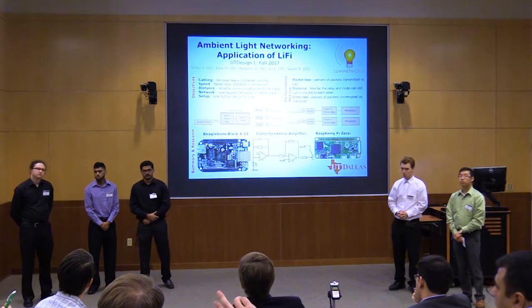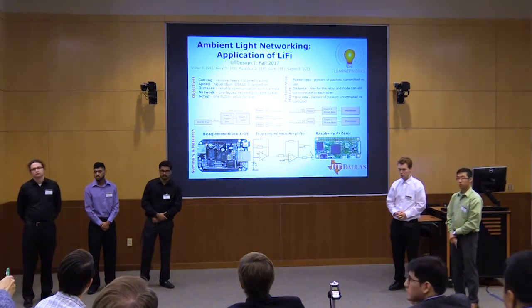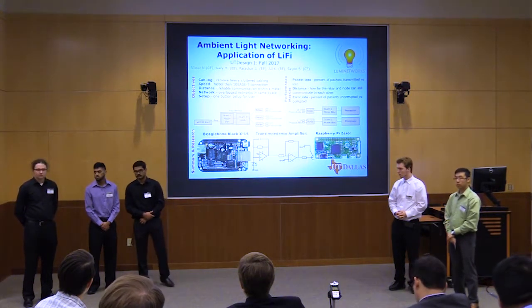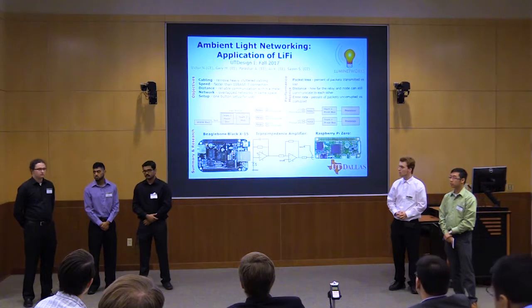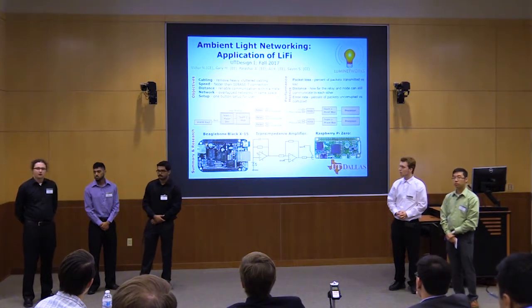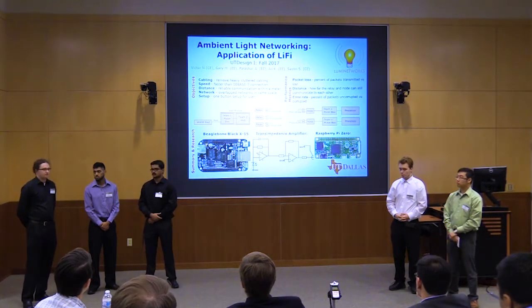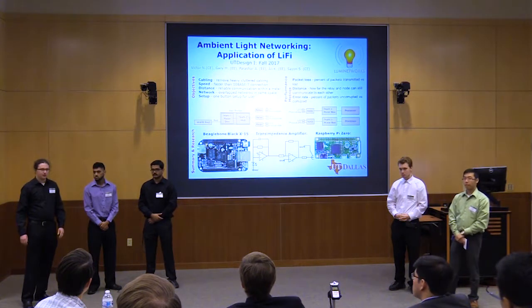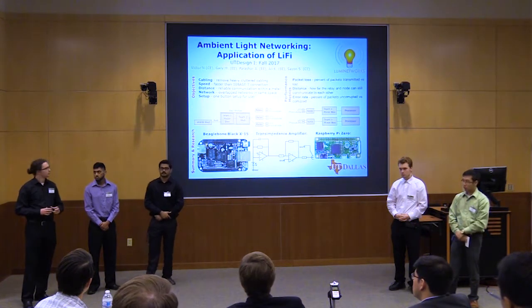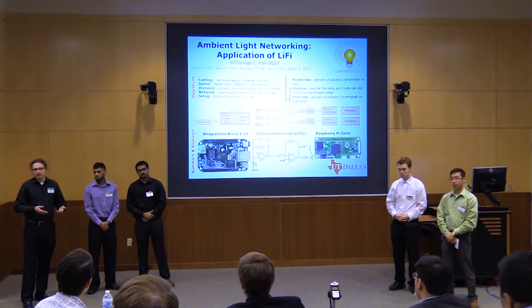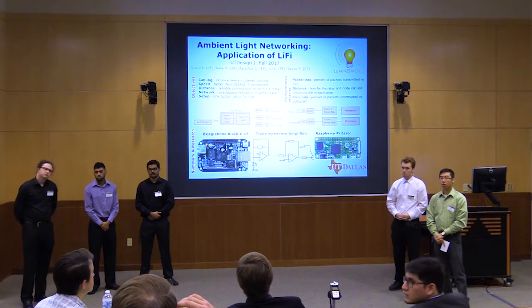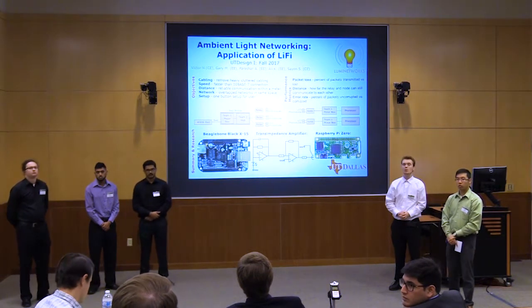And what about the error rate? How does the transimpedance amplifier relate to the error rate? The noise of the amplifier can affect that, as well as its sensitivity or its gain, because if you don't have enough gain, then our receiving BeagleBone or Raspberry Pi cannot interpret the signal. The goal of the project is to remove cabling.